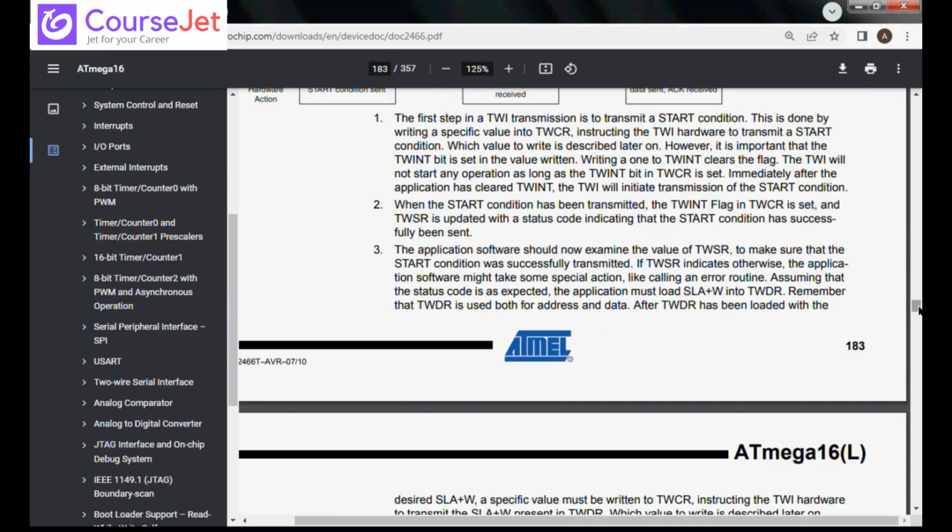For timers in the 8051, we have TH0, TL0, the TMOD register, the TCON register, and PCON, I guess. So 4 registers are related to timer, and different microcontrollers have different ones. You can simply understand the general concept behind these things. You cannot remember registers; to check a register, you have to go to the data sheet.